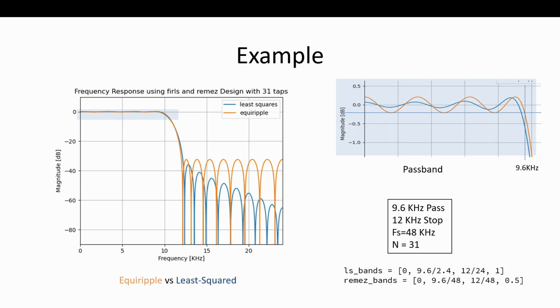When you have something here where each one of these is folding in and it starts accumulating up, this is good for that as well. So if you are doing any like polyphase filter implementation, for example, or resampling, and you're designing the coefficients for that, don't use Parks-McClellan, use least squares. But it's my go-to, use least squares.